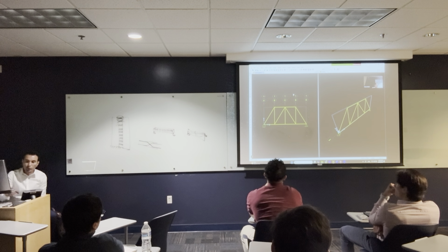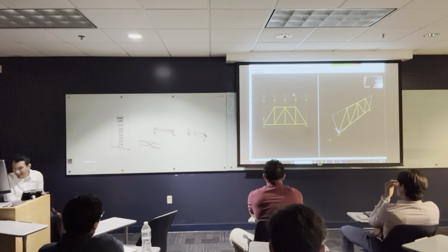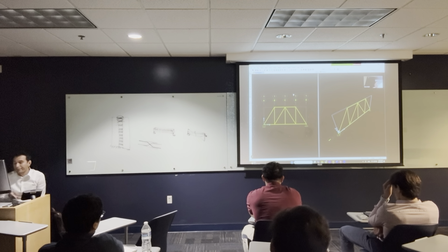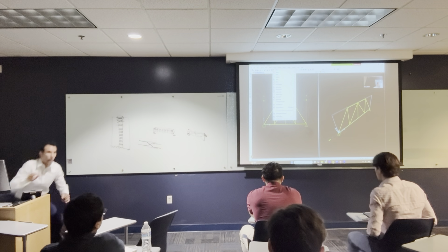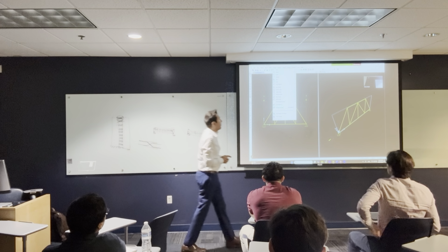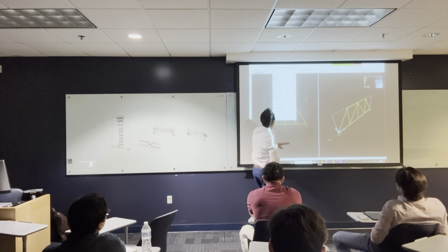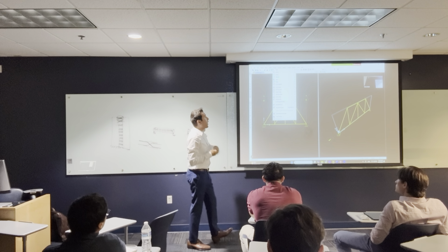When you select this, you will find something down here. It says how many joints are selected. It says 2 points selected. And I'm gonna go back to assign. Assign is always for assigning loads, assigning restraints, assigning sections. All these you can do from that side. Right now, I wanna assign.